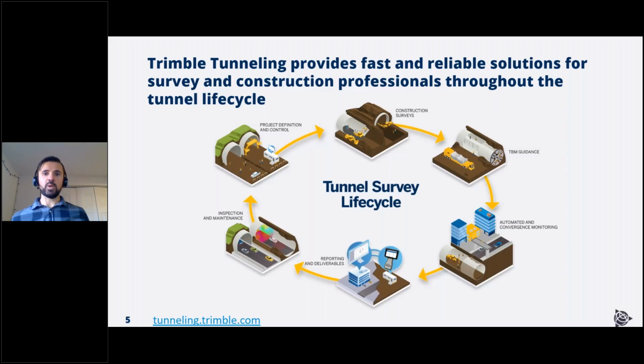Now, from that perspective, I look at the surveying piece of a tunnel as a life cycle, as there's a variety of areas throughout the tunnel life where you need surveying, where you need geospatial data, whether it's the start of the project, starting in the upper left-hand side where you're talking about defining the project, you're collecting the initial data for the site, the topographic surveys, you're doing the geodetic control, setting it up for the tunnel that will be built. And then you move into the construction process, depending on the type of tunnel, whether it's a drill and blast tunnel, whether it's a TBM, and a variety of other methods for building the tunnel.